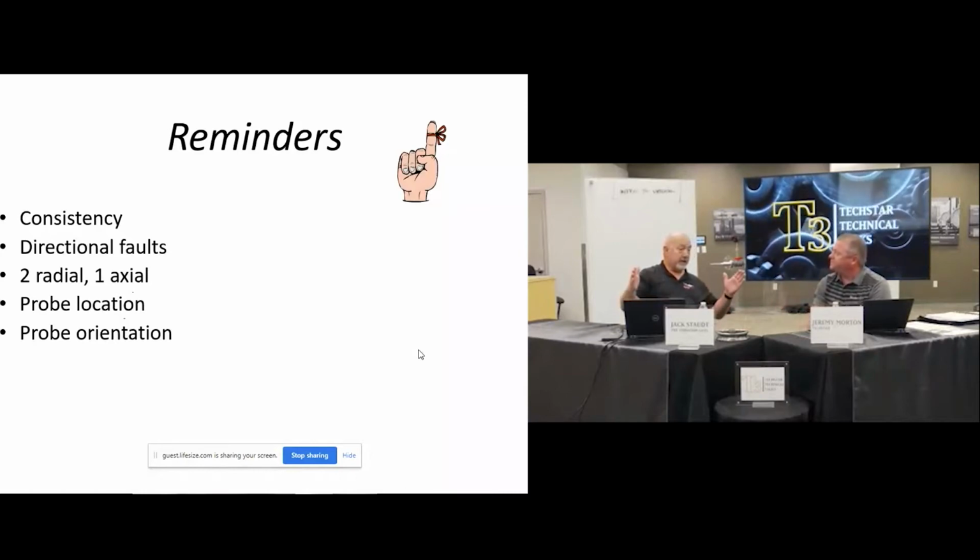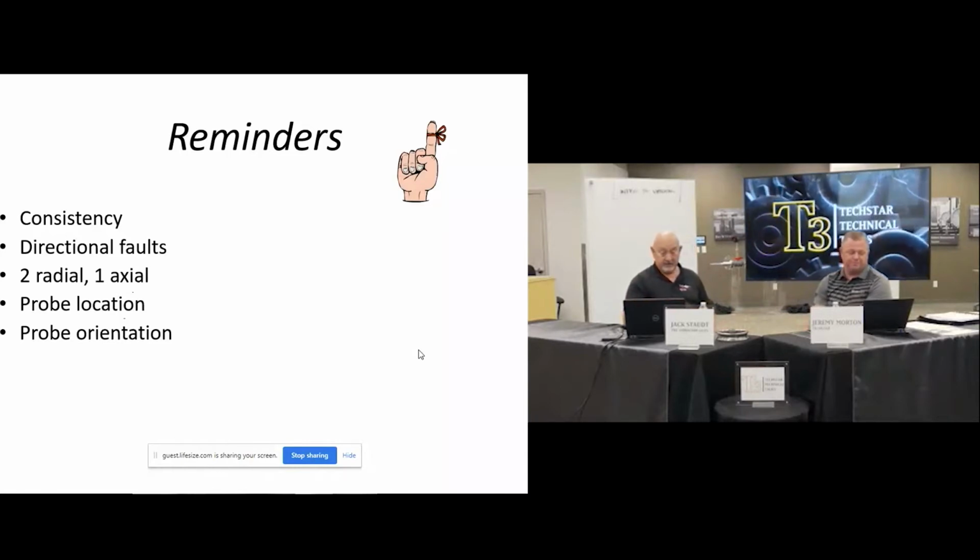You may have that much span of a fan guard from the bearing. But like I always tell everybody, it's better to take data here than not have any. Maybe you find the bearing at its third stage of failure because of the distance. You may not be able to catch it at first and second stage, but at least you're getting something.